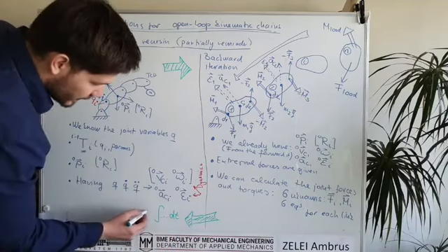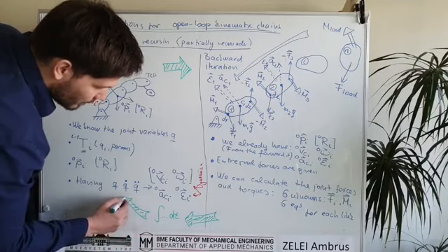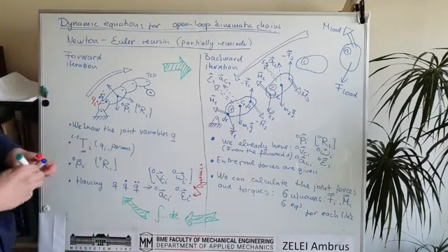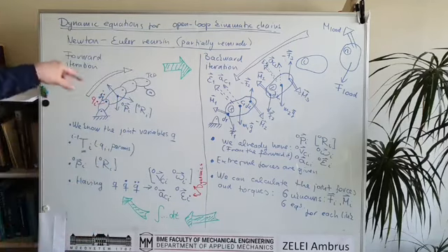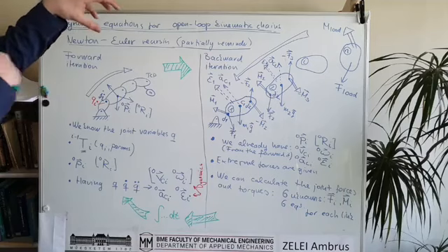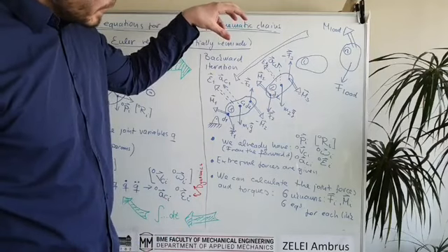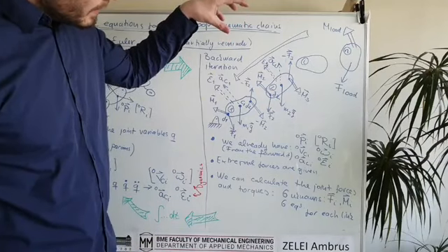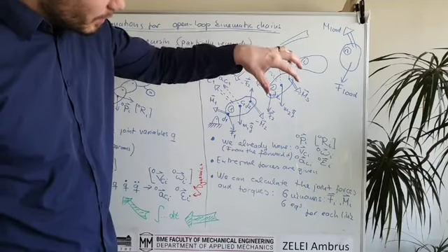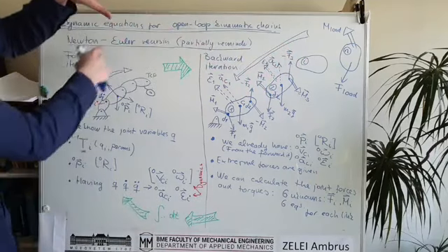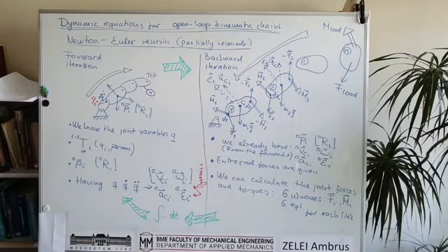And if we integrate the accelerations, then we will go back again to the forward iteration, because then we will have a new configuration of the robot. Okay, so the iteration thing is that we calculate the configuration of the robot, we take the forces and torques, we will have the acceleration, and we can calculate forward in time. So we will be in a new configuration, and then the whole thing has to be done again. So this is the idea.